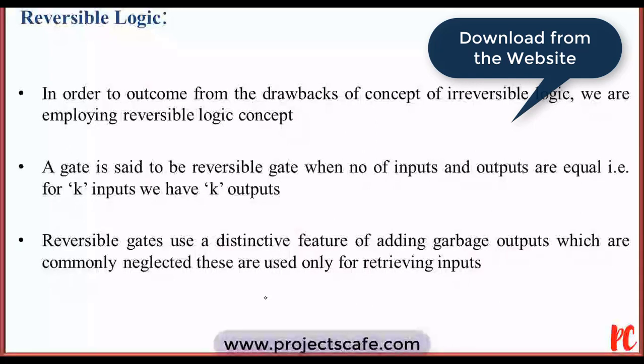A reversible logic gate is a memory-less logic element that realizes an injective logical function. Any gate that preserves the same parity between input and output is called a fault-tolerant gate. This can be done by using the double Feynman gate, Fredkin gate, Feynman gate, new fault-tolerant gate, Islam gate, and modified Islam reversible gate too. A reversible circuit without constant inputs realizes only balanced functions on all outputs.